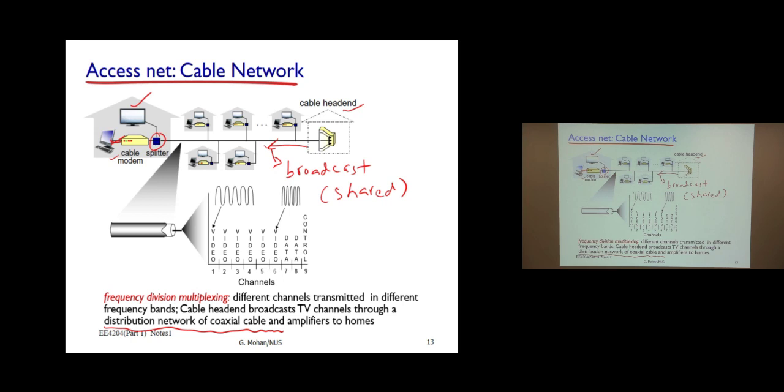Is that fine? And obviously nowadays these TV service providers have control over it. They provide a set-top box through which they control which channels you can watch and which channels you cannot watch based on your subscription. Otherwise, as far as the cable is concerned, it carries all channel signals until your home. So now the question is, can we make use of some TV channel bandwidth? Let's say there are two standards, 6 megahertz or 8 megahertz bandwidth used for every TV channel. If we can make use of the TV channel bandwidth for data transmission, then we can use that for internet purposes.